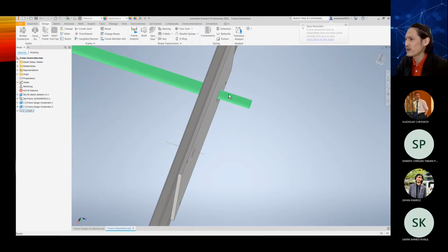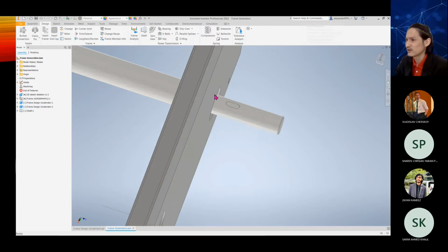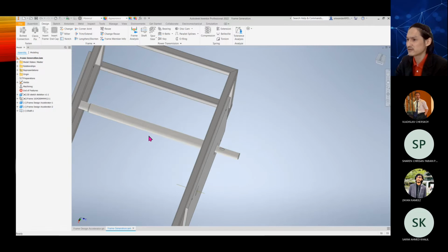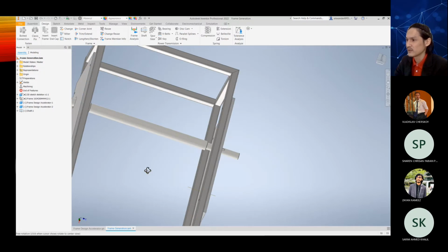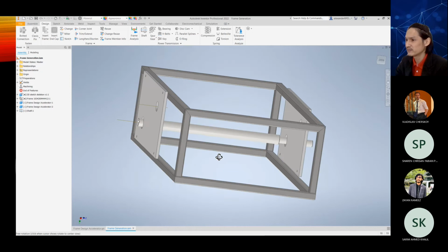I know I need to adjust a little bit up because keyway over here is too close. So later, if I put in the gear there, then there will be a collision over there. But this is how we can get our shaft very fast. And when you do dimension in the technical drawing, then you can bring them out already.